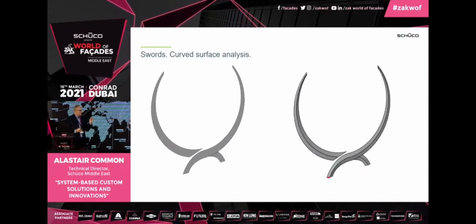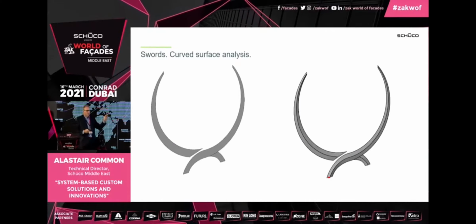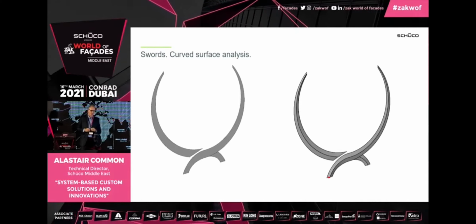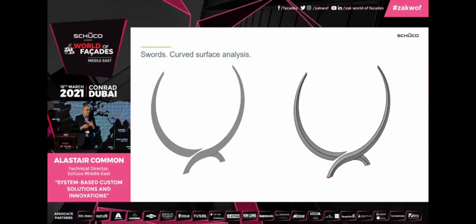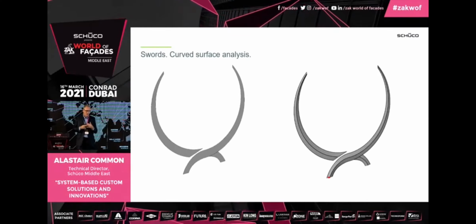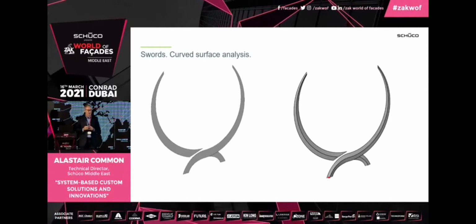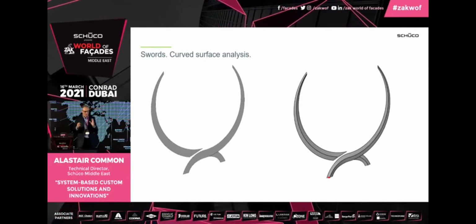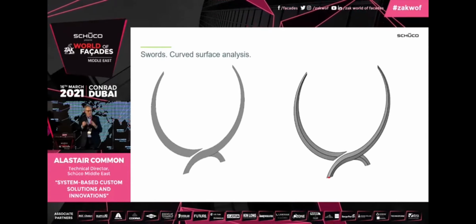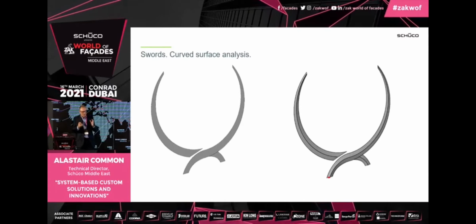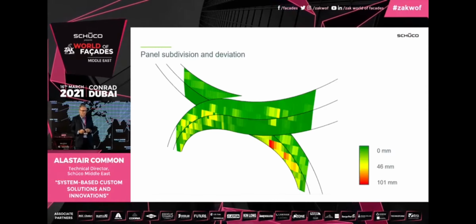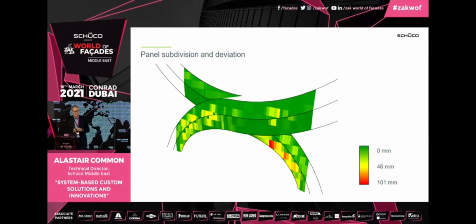So these elements here. And there were some real key challenges with this facade which we had to overcome. Firstly, they had to be in a unitized facade. There was no access from the outside because as part of the final negotiations, our partner basically gave a cost saving to avoid the need for external access. So these aspects started to increase the challenge. And at the same time, there's also cold bending in there. So just to make things a little bit more exciting.